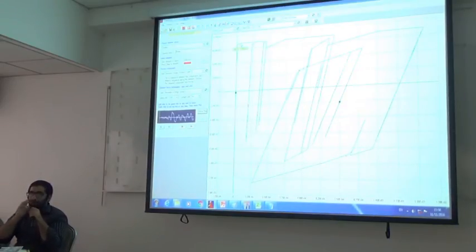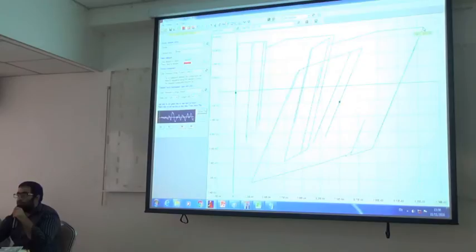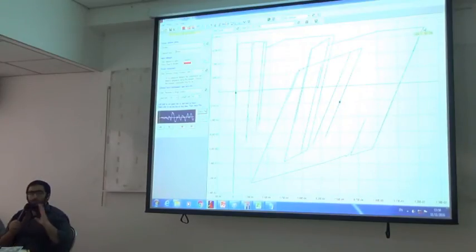The capacity that I defined, if you remember, the number was 0.025, right? And if I move further ahead, you can see that at this point, the moment still does not increase too much because now the girder has already yielded, so the strain hardening is not that much, but the rotation is continuously increasing, right? You can see that the rotation at this point is 0.001289. So these are just some nonlinear girder results, and then we can compare the rotation demands with the rotation capacities, and then we will have the DC ratio for girder rotation, and then we will check it. Right.